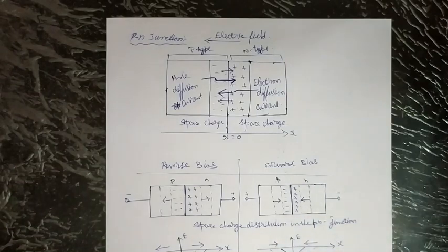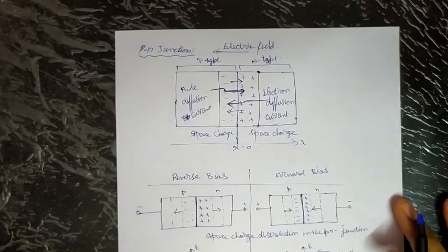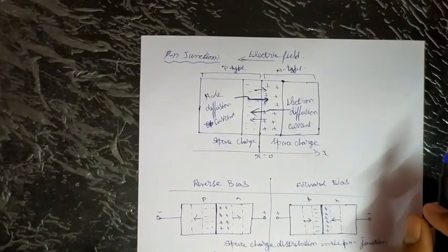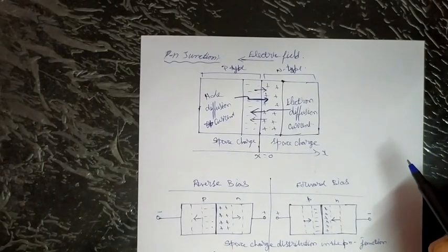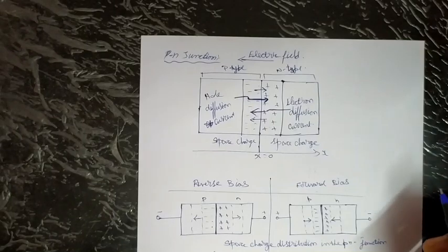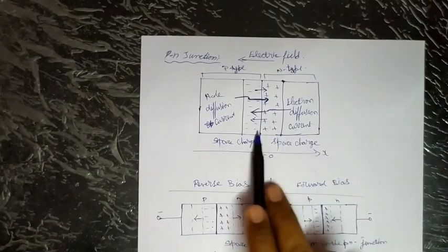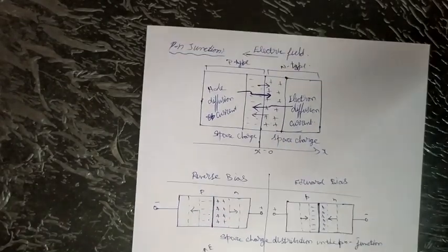The major part of an RF system deals with Schottky diodes and PN junction diodes. So today we are going to see about PN junction diodes. The physical contact of P-type with N-type semiconductor leads to one of the most important concepts when dealing with active semiconductor devices: the difference in carrier concentration between the two types of semiconductors. A current flow will be initiated across the interface. The current is known as diffusion current and is composed of electrons and holes.